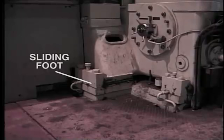After a short overnight shutdown, it is probable that the turbine shell will still be considerably expanded, while the rotor has contracted to provide a negative differential. This indicates that a hot start is required. Please make sure to check the manufacturer's recommendation for your particular machine.